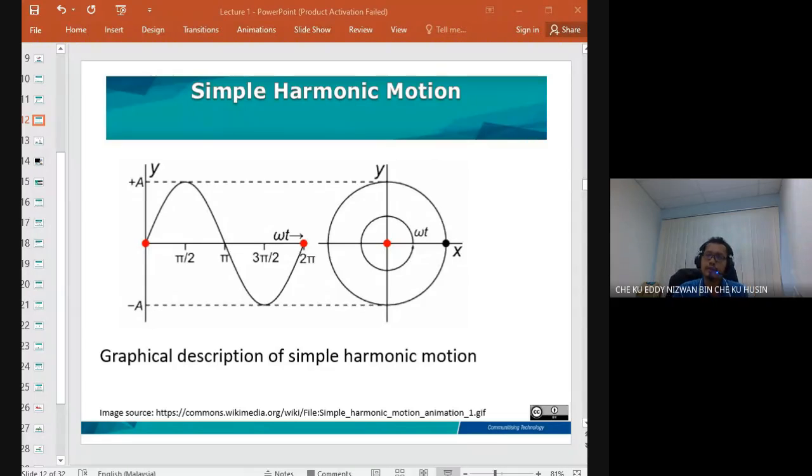Okay, so accelerometers perform very well for high frequency. If the vibration is high frequency, the time taken to complete one peak oscillation is very small. High vibration is different: it means the intensity is increased, so a high amplitude.